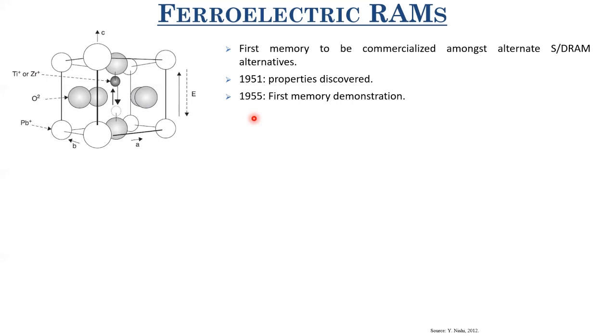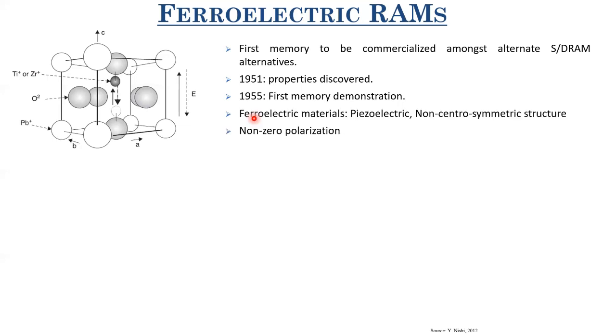And also they were low power consuming, because here the programming and erase is not by injecting some electrons somewhere, but because of changing of polarization. So they could be used for very low power applications. RFID was one of the first applications where ferroelectric RAMs were used. And by the 1980s or so, many industries and many startups in the US started coming up with commercial ferroelectric RAMs. These were memories which were much more mature than the NAND flash technology.